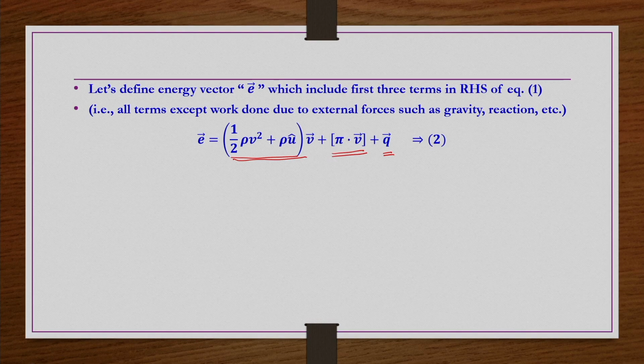Similarly, rate of heat out at x plus delta x because of the convection. Like that, if you write individual terms, there may be so many terms, and then that balance equation will become very clumsy. So, that is the reason we are defining an energy vector which includes all these contributions: the conduction, the energy associated with the molecular stresses, the internal energy, and the kinetic energy. All these parts we have added together and then defined our energy vector.